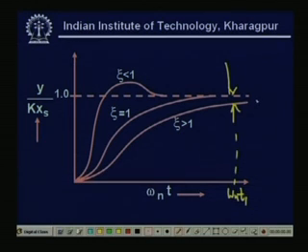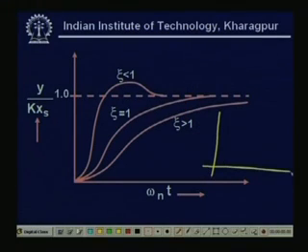This is important, because sometimes we cannot wait for a long time for it to reach that particular position. So it will also tell the settling time. We will see the definition of the settling time at the end of the lesson, because not always will you be allowed such a long time to settle down our system. It is also important in the case of underdamped systems, where I will get oscillation.